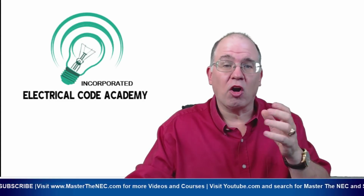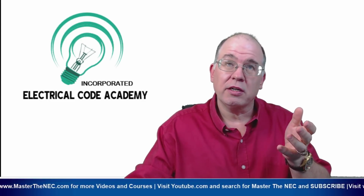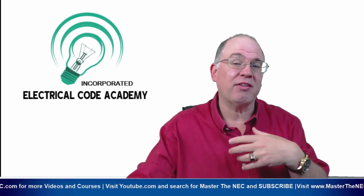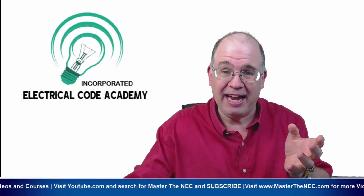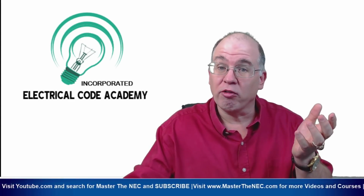Overcurrent devices are going to be sized at 100% of a non-continuous load and 125% of a continuous load. That's the rule, and it can't be any smaller than that. So let's look at what the rules say when we're sizing an overcurrent device.